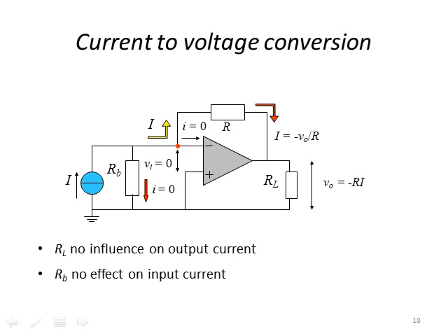Now how does this work? Well, as we've talked about in previous lectures, when you have the positive terminal connected to ground and the negative terminal connected to a feedback network and into your input, this is a virtual ground. So the input terminal is essentially set at 0. So your output is always going to be minus R times the original current, because you have this virtual ground.